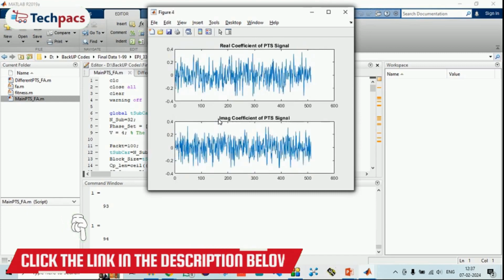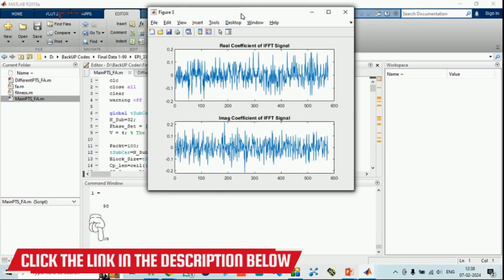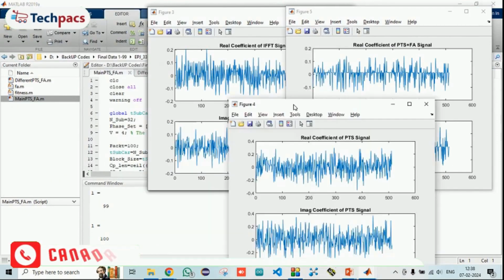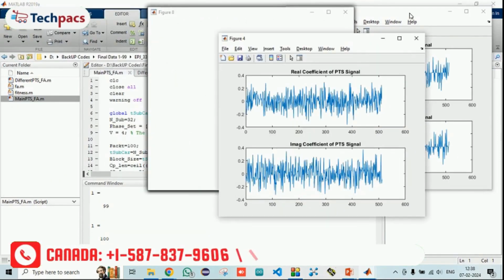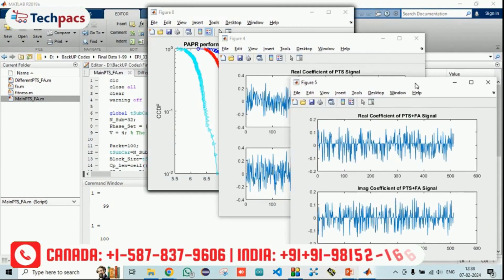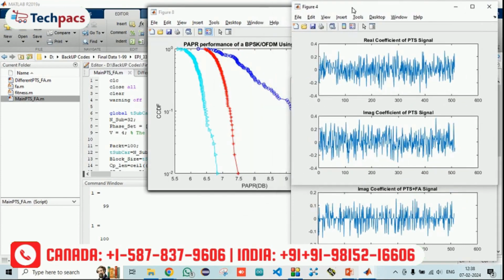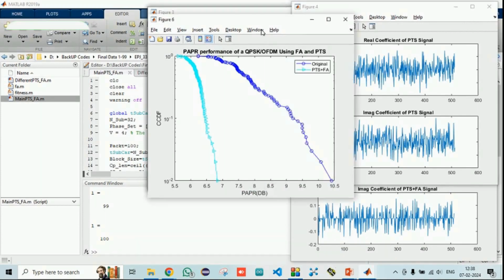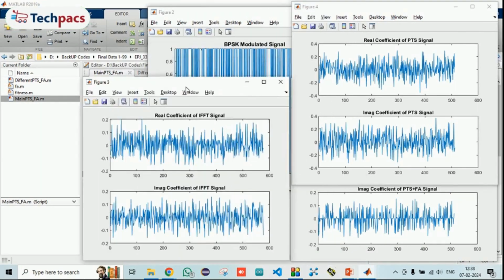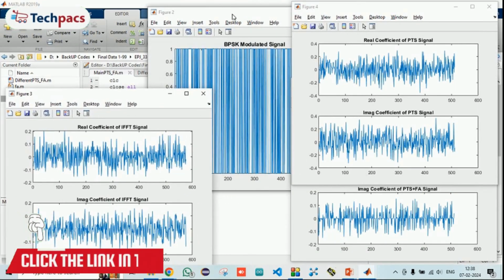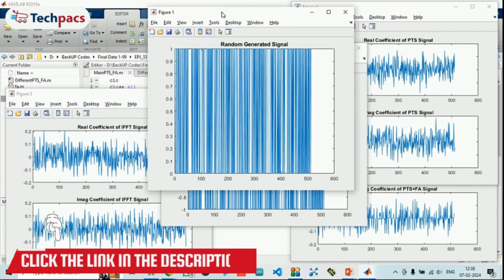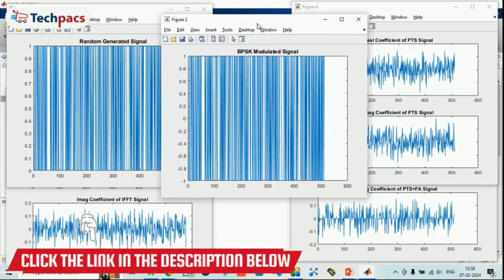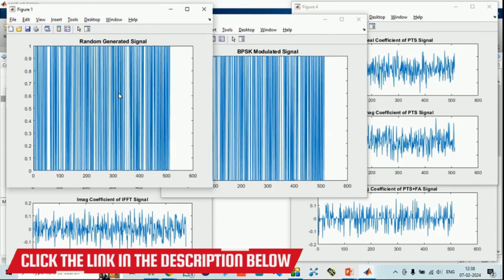So in the proposed system we have implemented the Firefly optimization algorithm in order to get the optimum outcomes in terms of the reduction of the PAPR. PTS was in the literature one of the best techniques, getting better results in many scenarios. So we are improving the PTS method, where the initial OFDM system has been implemented and analyzed with certain parameters. As you can see, this was the signal that we have generated.